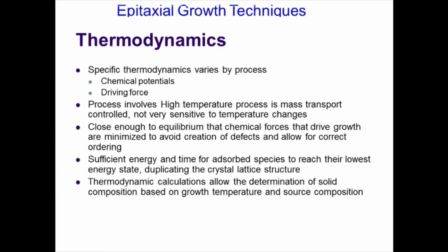When you talk in terms of vapor phase epitaxial growth techniques, thermodynamics comes into the picture automatically. Normally, before you do the growth process, they theoretically calculate the optimum or approximate growth parameters, namely the partial pressure of each gaseous species to be transported inside the reactor, then the temperature of the substrate where the reaction will take place, and finally the related species get deposited on the substrate. So here, if you consider the thermodynamics, you come across two different categories, that is the processes, chemical potentials and driving force.